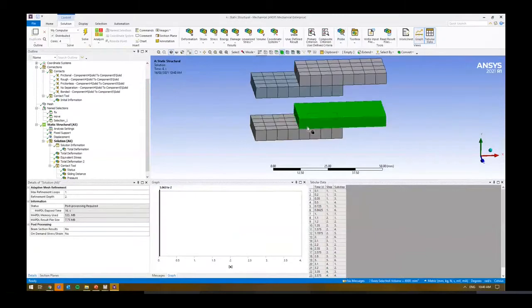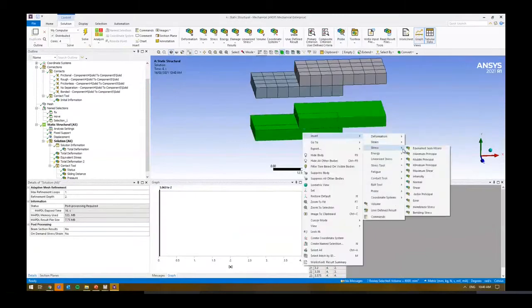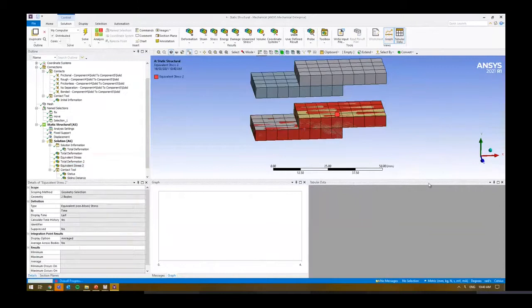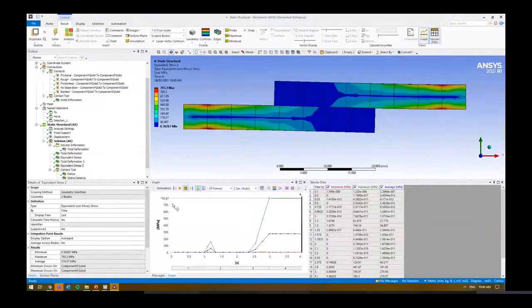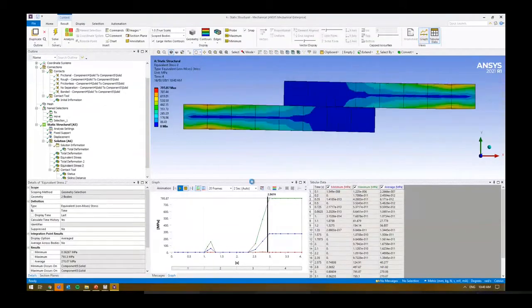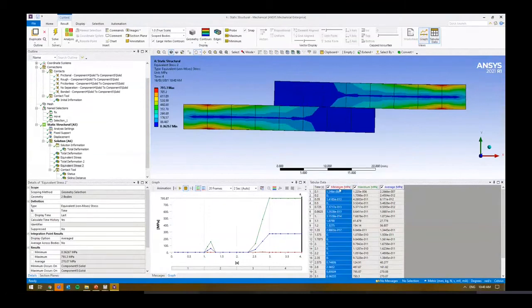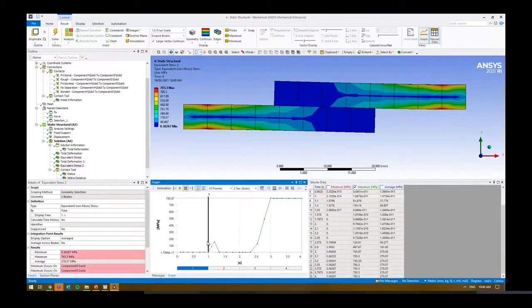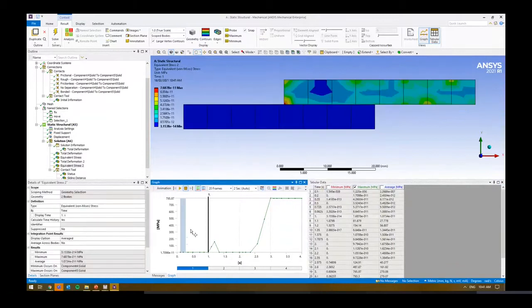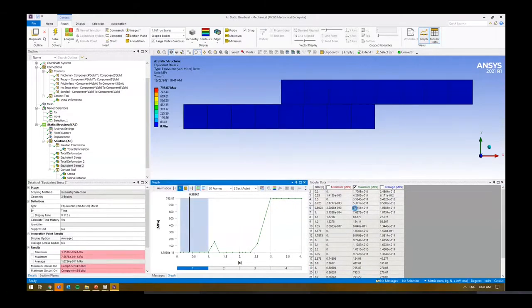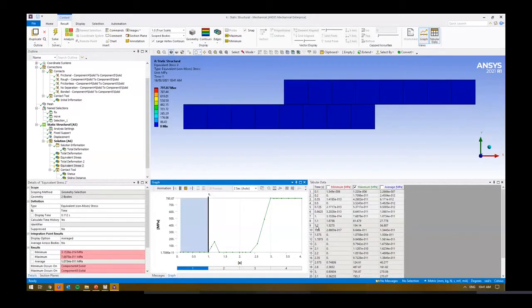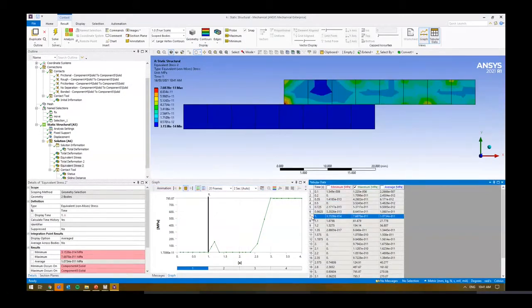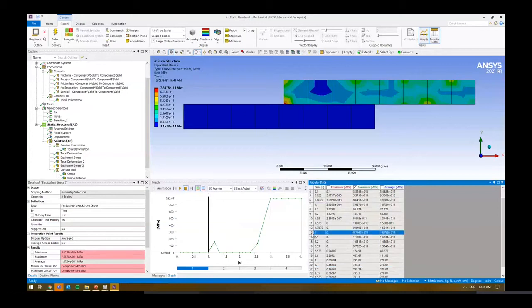Let's also have a look at things like the stress on that particular component. Again, we can chart it and you can see what's happening. I'm not caring too much about the minimum or the average. I just want to care about what's happening with the max. You'll notice for the very first time, there's just a bit of sliding, but it doesn't really look like there's too much stress in there at all. I mean, what's the maximum? We can look at the maximum, e to the negative 14. Not much is really happening there.